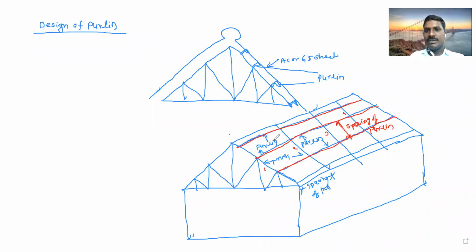Please, everyone, are you getting how the industrial building is there? The main truss is there. This is the length of the building. These trusses are rested at some spacing. This is the spacing of truss. It will be 4 meters, so the first truss is at the first point, then after 4 meters the second truss along the length.